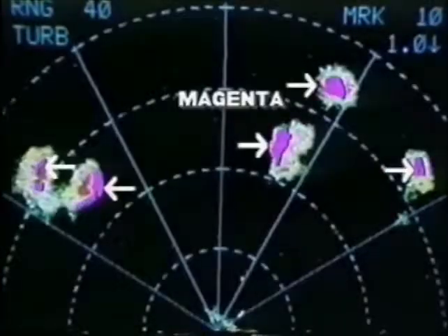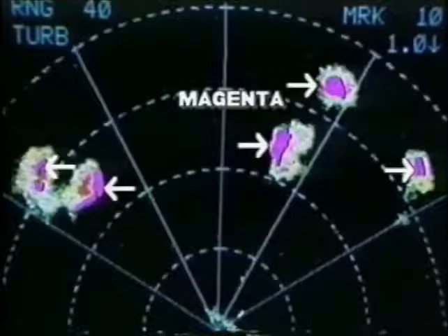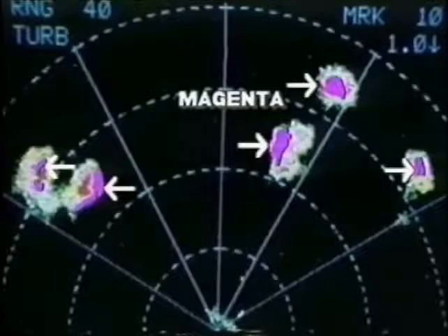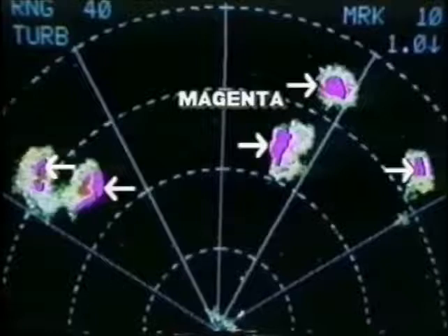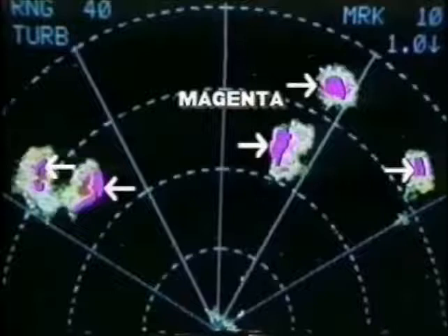The system displays the areas of turbulence as a magenta overlay on the radar's normal weather presentation. On older EFA systems, turbulence is displayed as red. The turbulence display operates out to a maximum range of 40 nautical miles. Ranges in excess of 40 nautical miles may still be used while operating in the turb mode. On these longer ranges, the first 40 nautical miles operates in the turbulence detection mode, and the remainder of the displayed range operates in the normal weather mode.